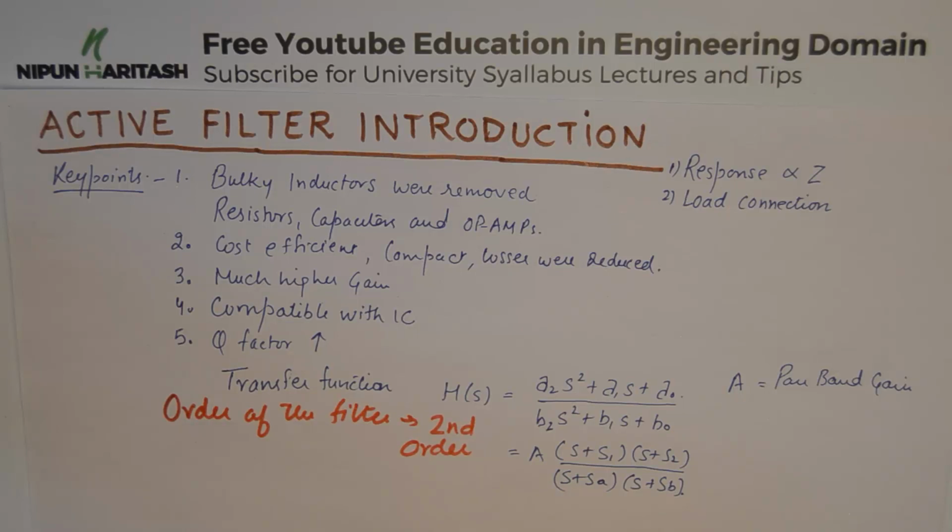We can say that the fact is, a second order filter introduces a 1 upon omega square form at high frequencies, and at the cutoff frequency the attenuation is much sharper, because it is omega square in the denominator.